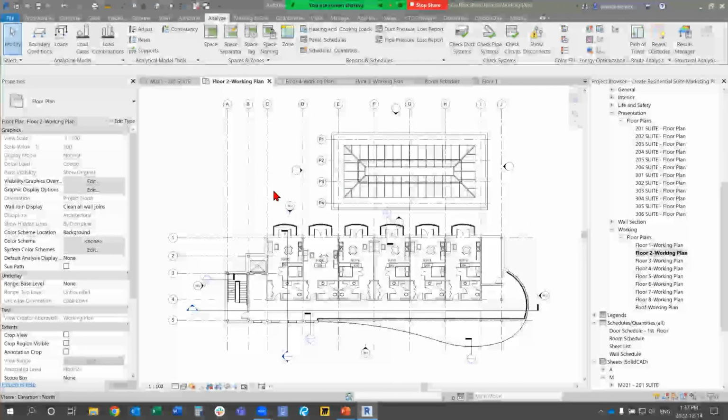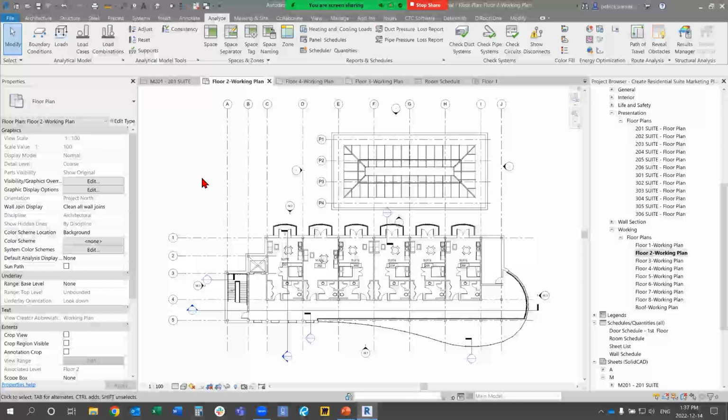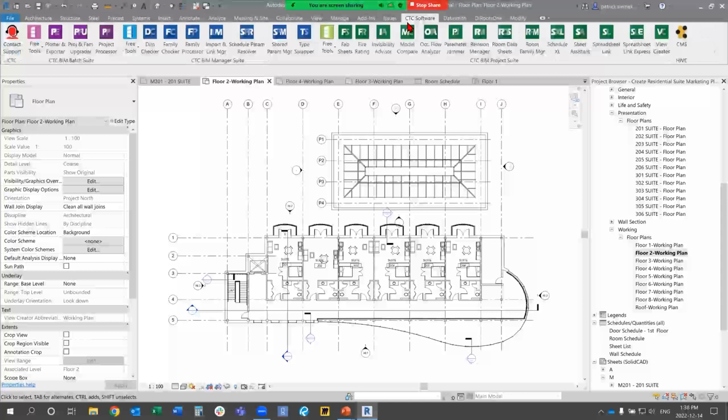Because in our architectural drawings, we need to define the rooms, for example bedrooms, to check what the area is, because it has to be compliant with the building code. So defining everything as one room and having all the non-bounding walls is not really an option then. Yeah, so that's the thing. The tool is just looking directly for a room. You can't do a combination of multiple rooms as one.